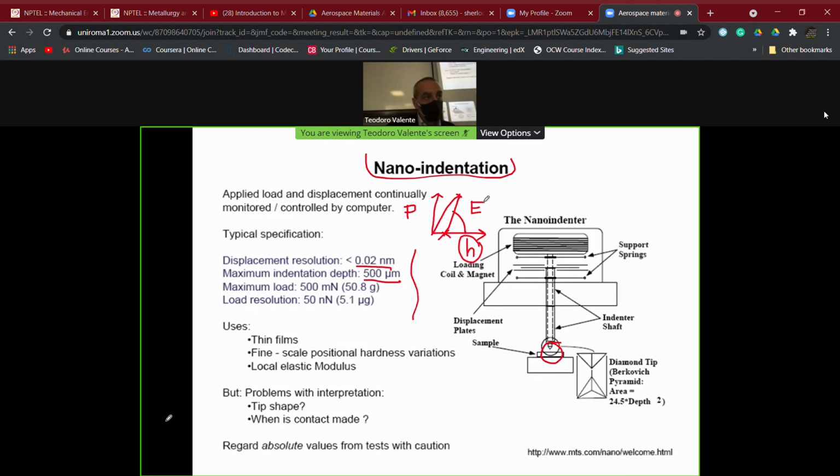If we do have a suitable relationship, numerically speaking, between hardness and yielding strength of the materials itself, we can have an estimation of the yielding strength of the surface. If we use a model in terms of presence of crack propagation on the tip of the impressed area, we can have an estimation of the fracture toughness of the materials itself.